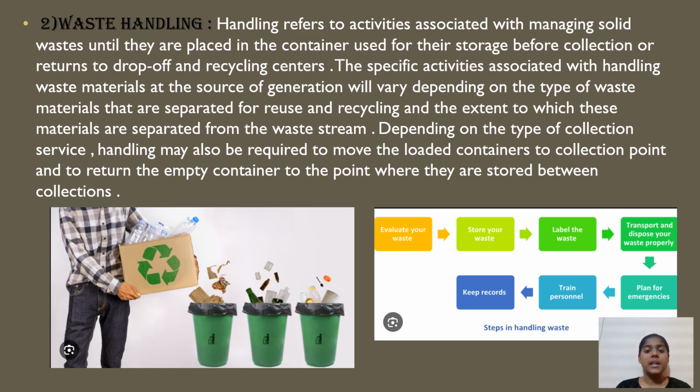Second, waste handling. Handling refers to activities associated with managing solid waste until they are placed in the container used for their storage before collection, or returned to drop-off and recycling centers. The specific activities associated with handling waste materials at the source of generation will vary depending on the type of waste materials that are separated for reuse and recycling and the extent to which these materials are separated from the waste stream. Depending on the type of collection services, handling may also be required to move the loaded containers to the collection point and to return the empty containers to the point where they are stored between collections.